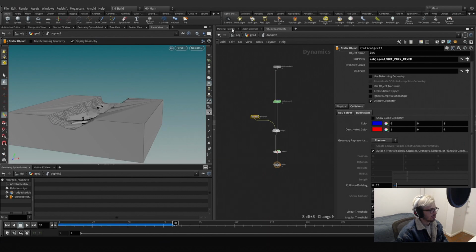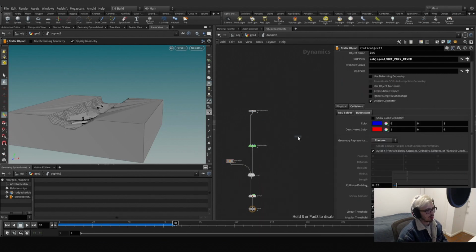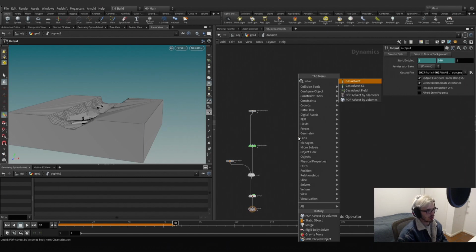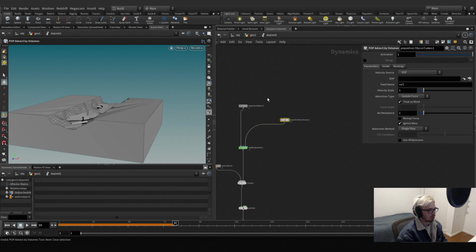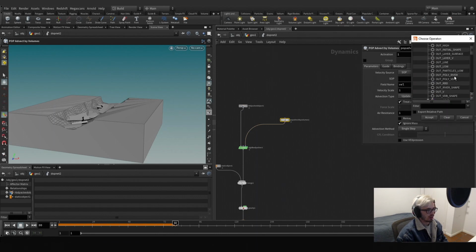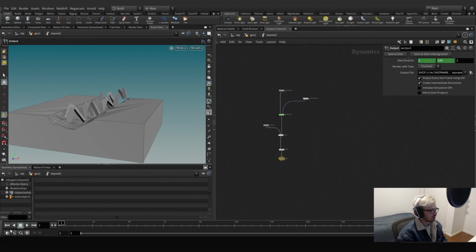But we want this to move with the water. So far it's not working. So let's use advect by volumes, advect by volume, yeah, and use in the post solve grabbing our out B, and instead of velocity use B. We will update the force and we will see what happens. This is taking a little bit long because I should have used a low resolution